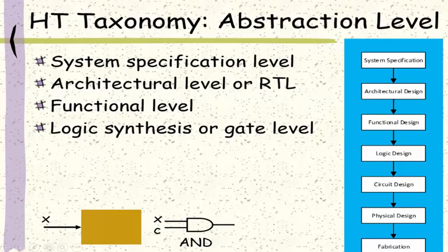Similarly, this can also be done with a 2-input OR gate. However, in this case, the building block will be disabled when X is set to be 1, and it will be enabled when X equals 0. So in the normal case, we set D to be 0, to let the system behave normally. And once we try to disable the system, we set D to be 1 to disable the block.